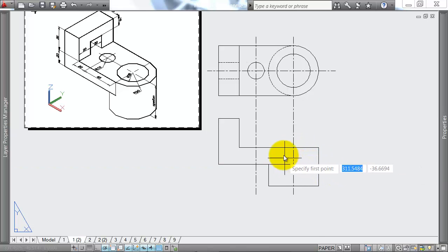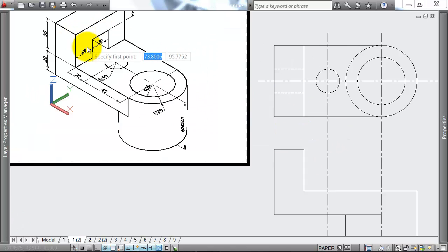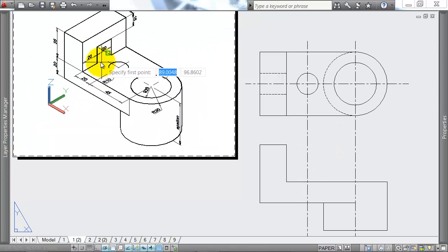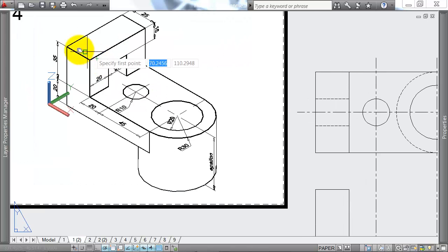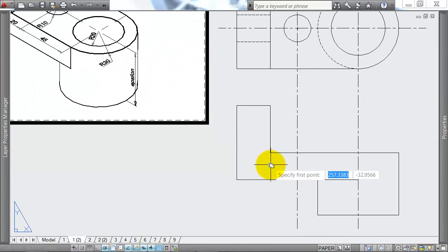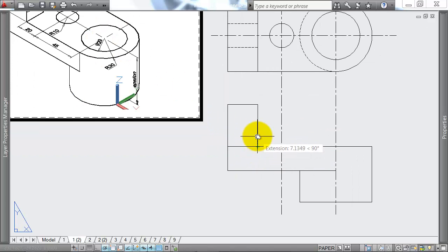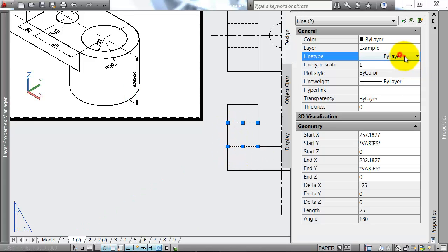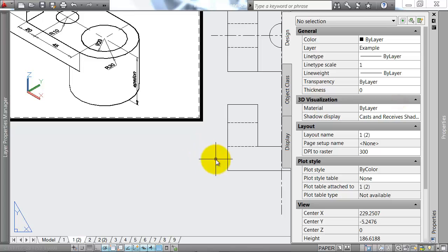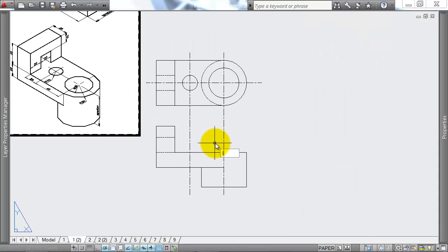Now with hidden lines in this shape, we need, again, this notch in here is 20 units wide, and it is 35 minus 15, so 20 units high as well. So I'd have one hidden line for the bottom part of the shape, and one hidden line 20 units up from that. Okay, we've also got hidden lines in line with the edge of this circle, so this is going to show where the hole in the circle is here.